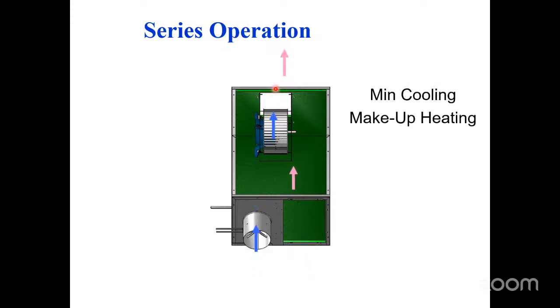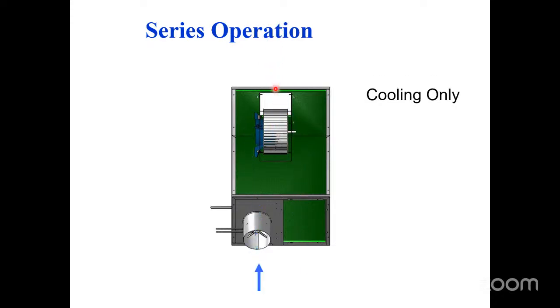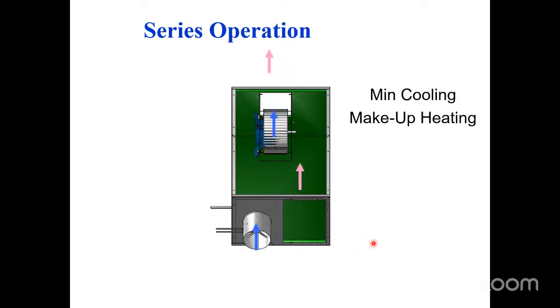When I'm doing that, I will have it at minimum cooling position. So minimum meaning the lowest amount I'm allowed to have for that zone based on its ventilation needs. When I go to a cooling scenario, then that damper opens up and all my air comes through that damper and goes through the fan and down the duct. And nothing comes in the plenum. There's no damper here. I don't need a damper. If I'm providing you 1.5 inches of static here, and this guy's pulling air out of this box, it's going to pull it from the pressurized pathway and not this other open pathway. So when you want full cooling, it all comes through there. Nothing comes through the plenum. But when you have minimum cooling and a little bit of heat to make a mix, that's when you've got air coming through both.